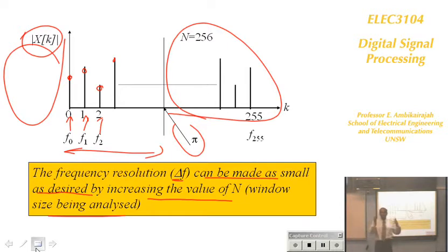For a stationary signal like sine waveforms, it's fine. But a non-stationary signal like speech changes every 20 milliseconds, so you can't have a large window. You have to analyze every 20 milliseconds. Otherwise the frequency spectrum that you get is a completely averaged spectrum, which is not correct, because the spectrum of the vocal tract and the resonance change every 20 milliseconds. So the window size cannot be made very big in real signals.